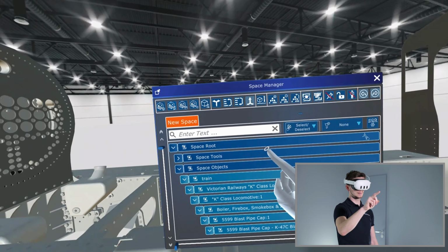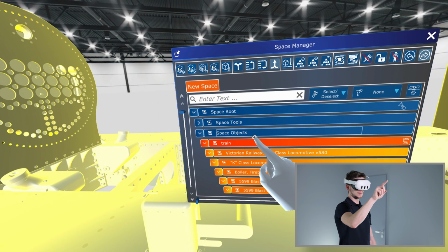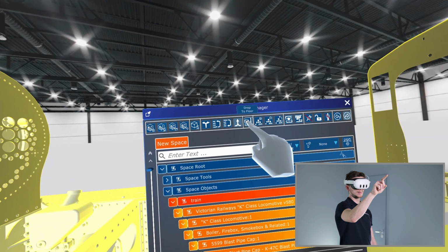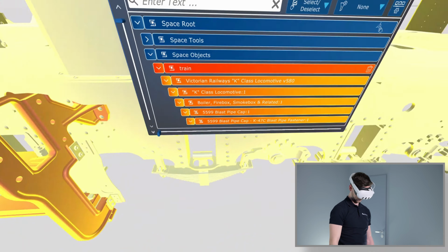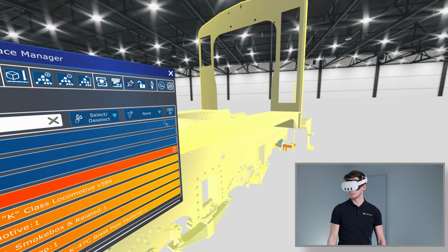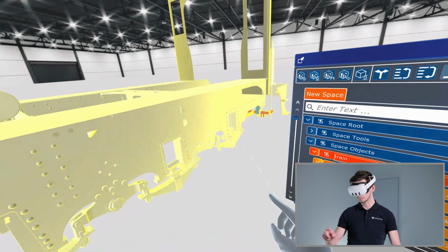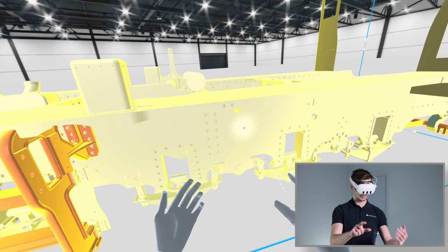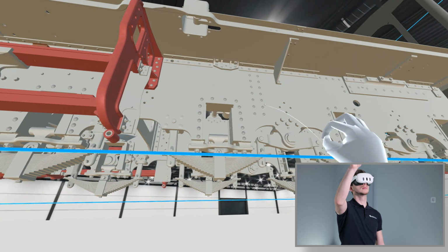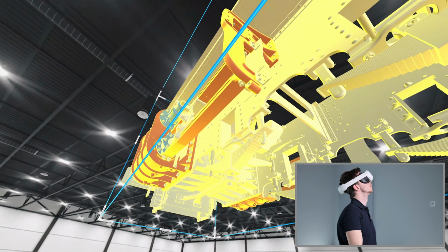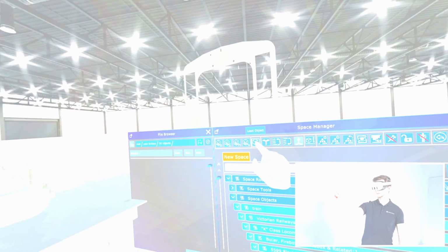On top of the Space Manager, there are different functionalities that can be used for different purposes. For instance, if you want to be sure that you are positioning your object on the floor, you can just quickly select and trigger the drop to floor. This way, the file will be aligned with the floor you have set up during the initial setup of the device. The selection in Space Manager can be used also in combination with Quick Access functionality like the bounding box. This way, it's possible to move the object freely in the space without considering any physics applied to the model.